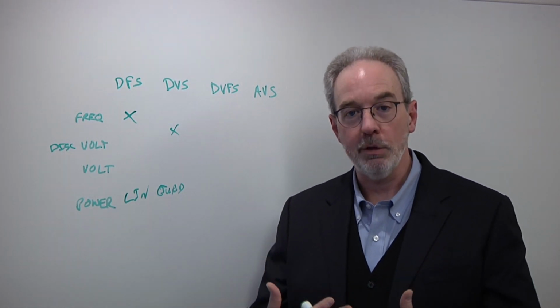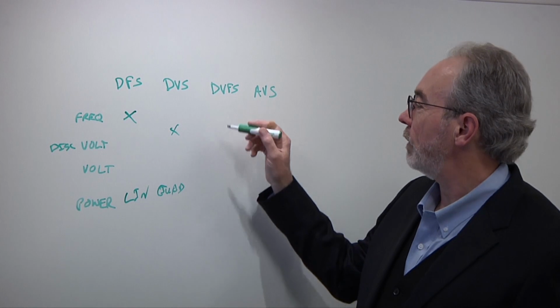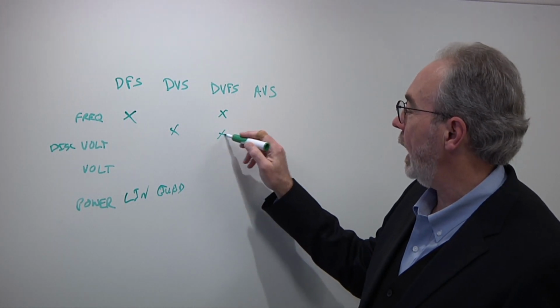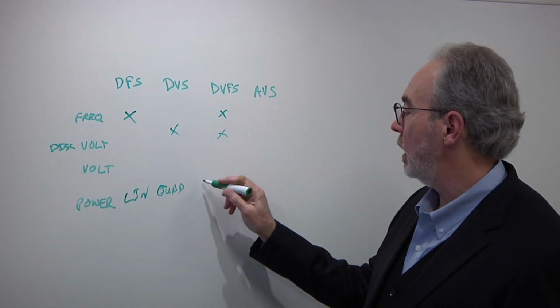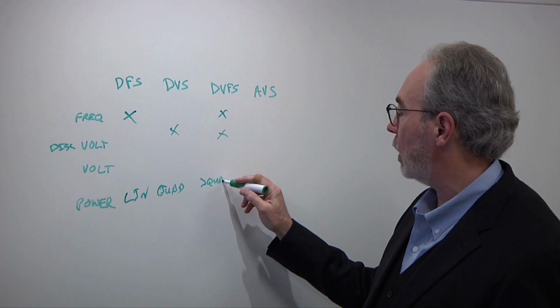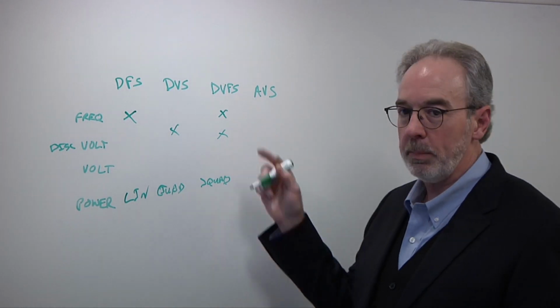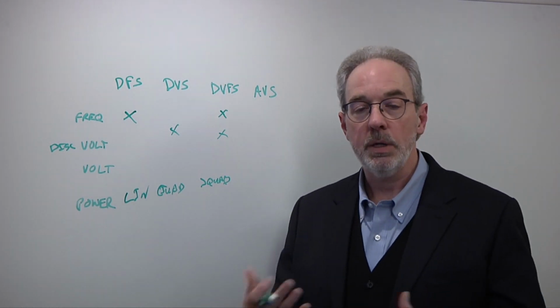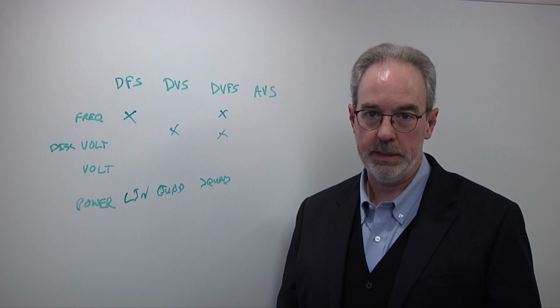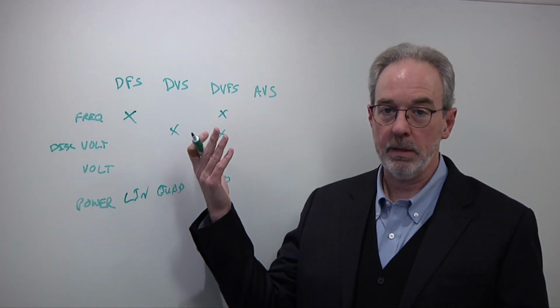When you combine those two, that's where you get DVFS, where you're manipulating the frequency and the voltage, again, in a discrete level, and you're getting slightly better than quadratic power savings. This is really the target. People are trying to do everything they can to get more robust and more power efficient designs. And so this is the technique that they're deploying.